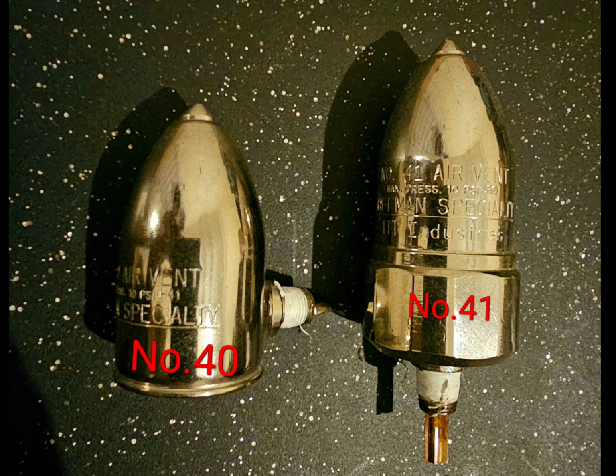And just to get back to the point I was making, the 3/4 inch vent will have, in addition to this thick bead over here with the hexagon slot, this thick 3/4 inch threaded nipple. And that right there helps it to hold its heat. So therefore, if you slap this onto a steel convector, chances are it's going to hold its temperature a little bit longer than the steel convector, and your radiator is going to start to cool down.